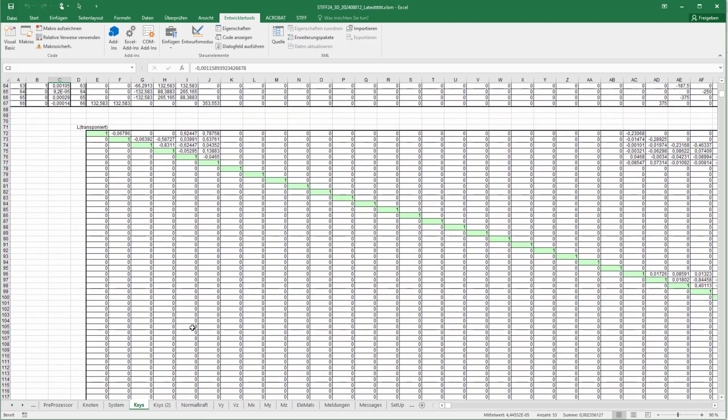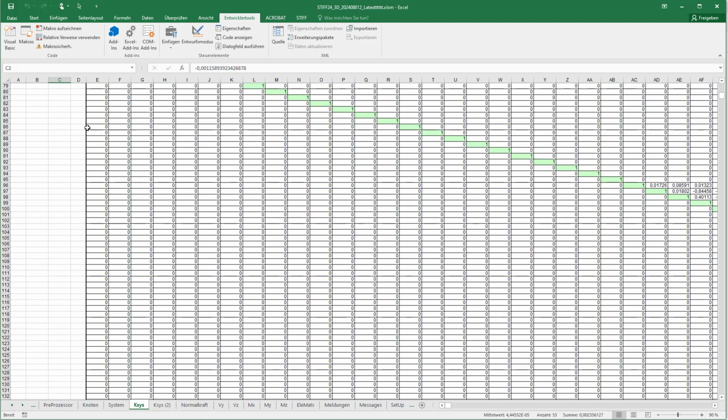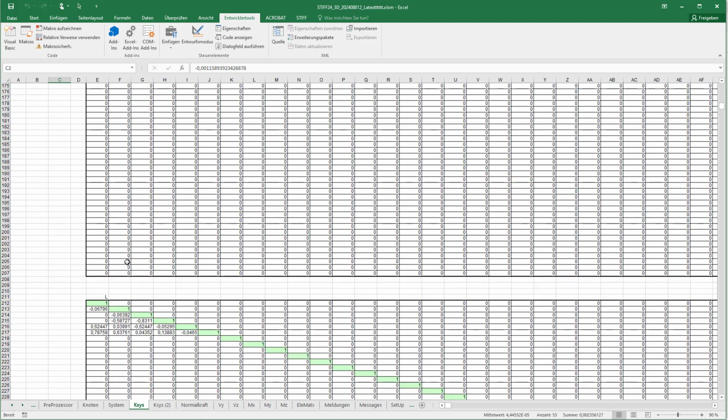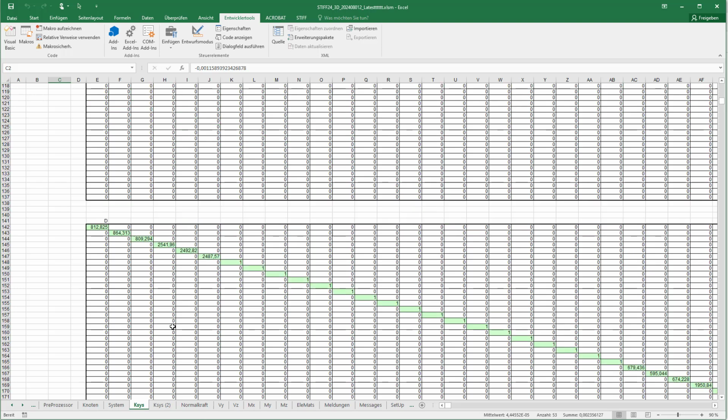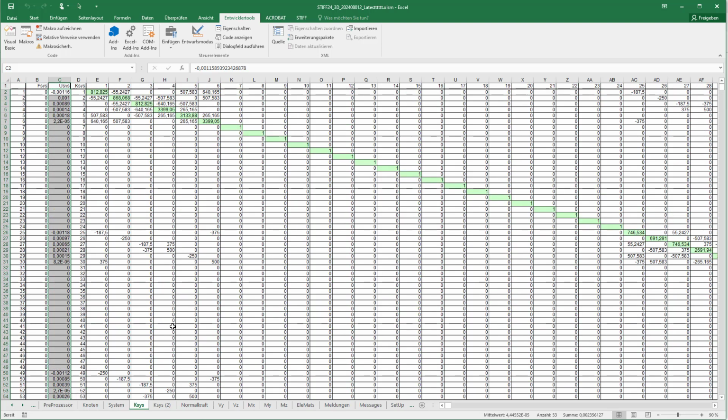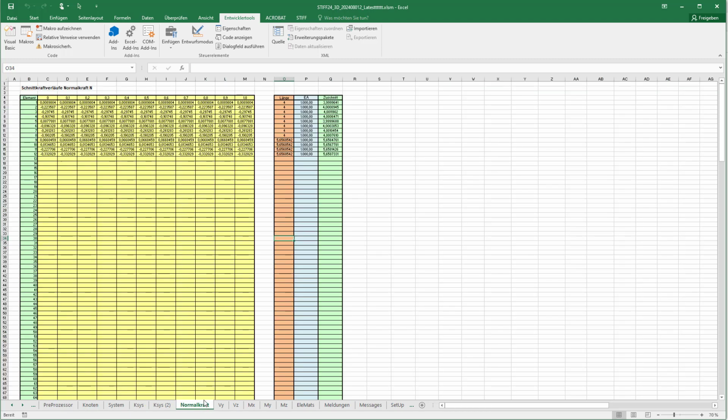And what you see below, that's the decomposition of the stiffness matrix in a lower triangular matrix, its transpose and the diagonal, the upper and lower transpose, if you are interested in equation system solution. Then you see the tables about the stress resultants.